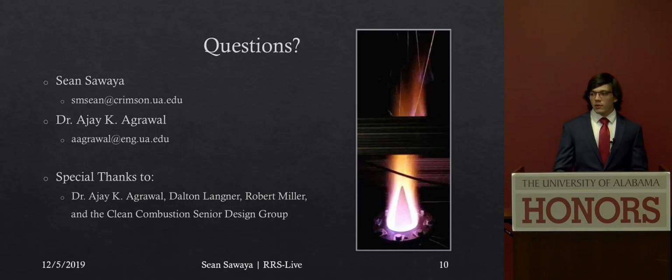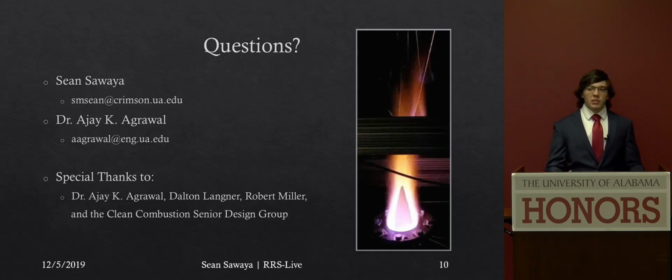Could you speak more to some of the optical analysis techniques that you'll be using? So we will be using two main different optical analysis techniques. The first will simply be high-speed videography. That will just give us general information like the speed of the wave, the cell structure within the wave, how long the wave lasts within the spiral, and other kinds of information. And we will also be implementing higher-level optical analysis techniques like rainbow Schlieren deflectometry, which will provide us with density gradient information about the wave as well.